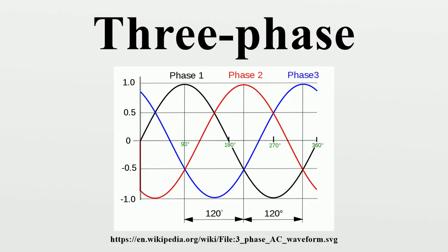Conversion to other phase systems, provided two voltage waveforms have at least some relative displacement on the time axis, other than a multiple of a half cycle. Any other polyphase set of voltages can be obtained by an array of passive transformers. Such arrays will evenly balance the polyphase load between the phases of the source system.